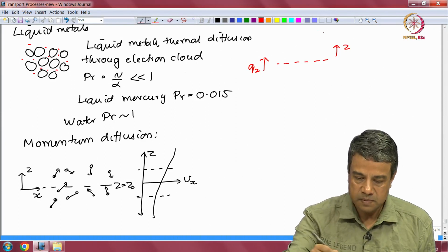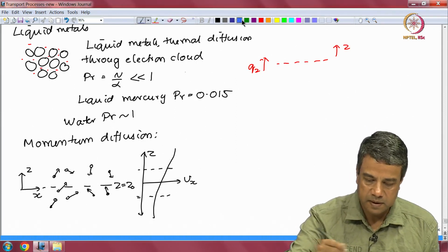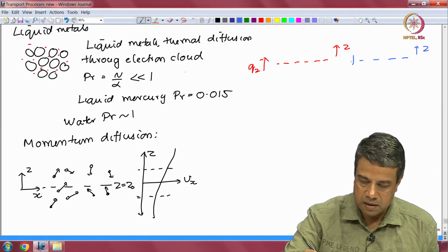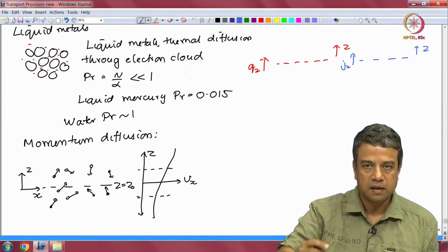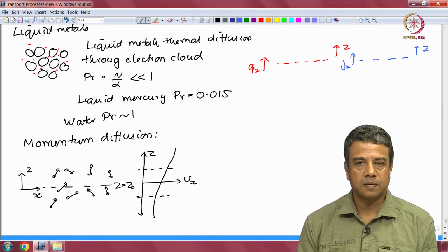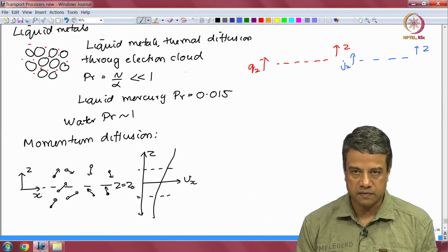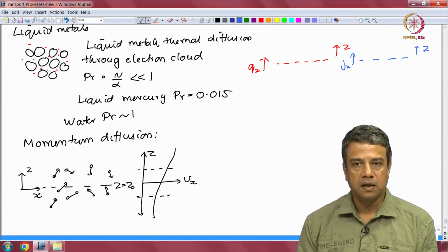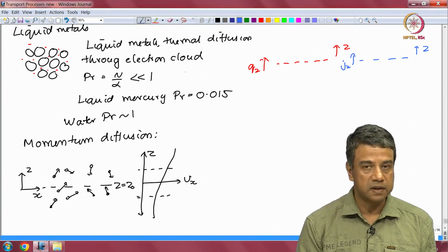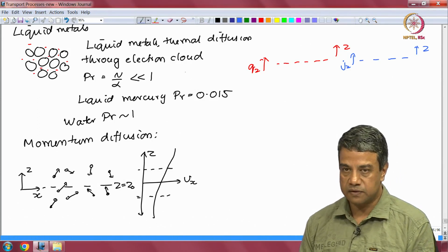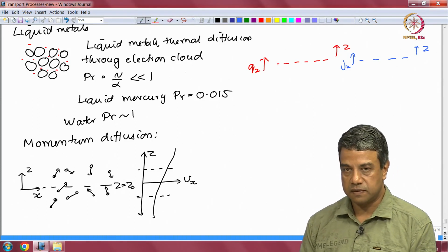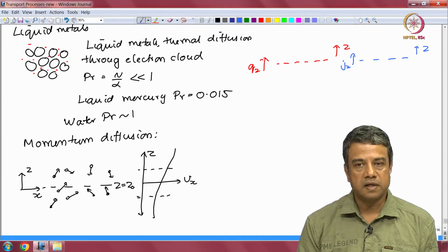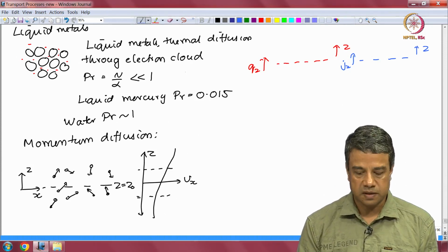Similarly for mass transport, the flux was defined as positive if it increased the mass in the volume above the surface. That was the convention that we used for deriving Fick's law for mass diffusion and Fourier's law for heat conduction. The convention used for momentum transfer is the opposite.